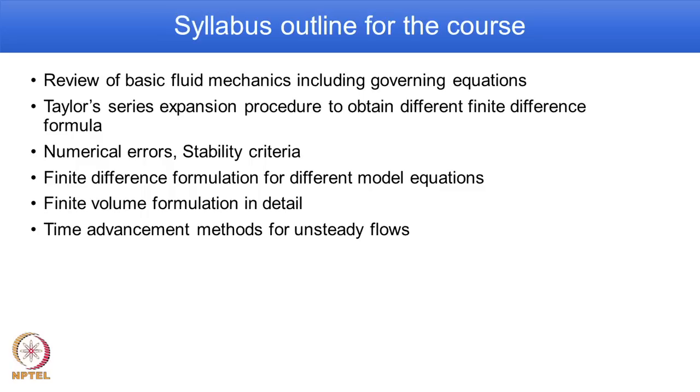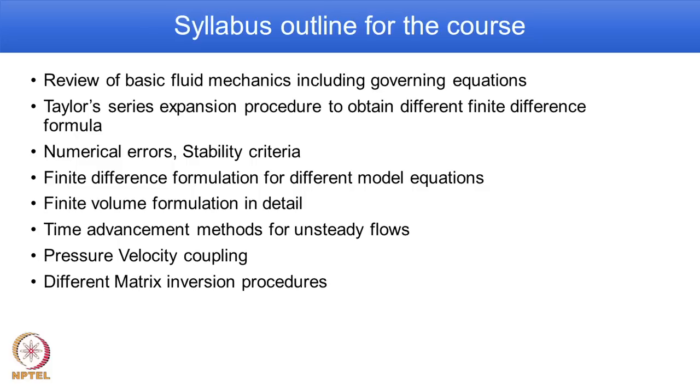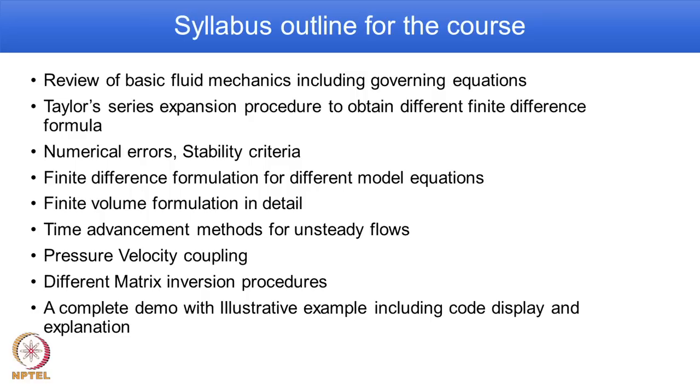How to do unsteady equations, which means time advancement methods for unsteady flows. Then another important procedure, what is known as pressure velocity coupling, which is linking the momentum equations and the continuity equation. All these equations when discretized will result in what is known as linear algebraic equations. Then to solve them you have to know different matrix inversion procedures. We will go over those procedures also.